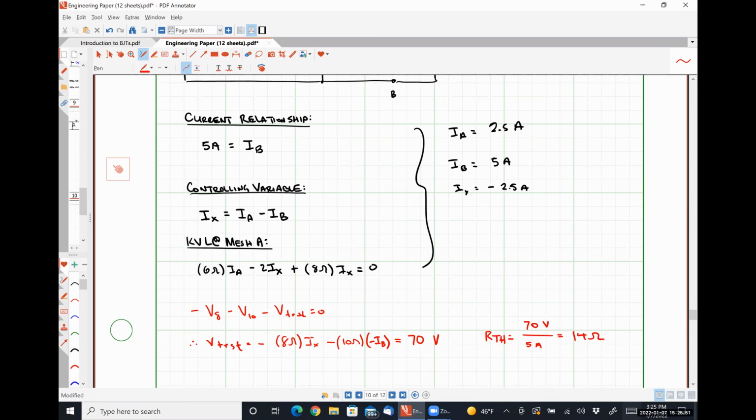So I believe on the in-class assignment that I give you guys, the first problem I ask you to work does have independent sources. So probably the most easy and logical way to determine the Thevenin resistance is taking V Thevenin divided by I Norton. But for the second problem, I believe you don't have an option. You have to apply a test source method to it. And on exam 2, I will absolutely give you a problem that necessitates the use of a test source method to solve it. All right, so that's Thevenin and Norton equivalent circuits. In-class assignment time.